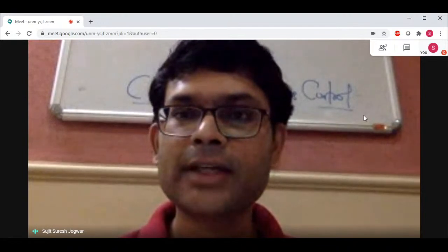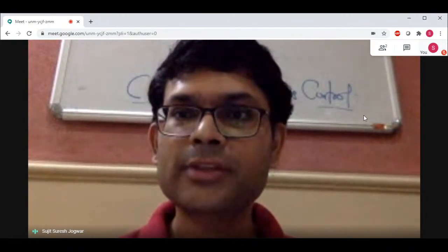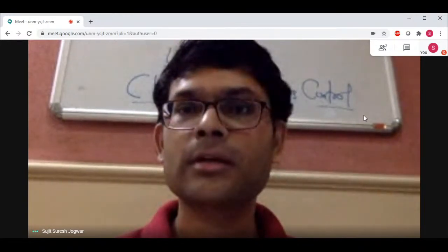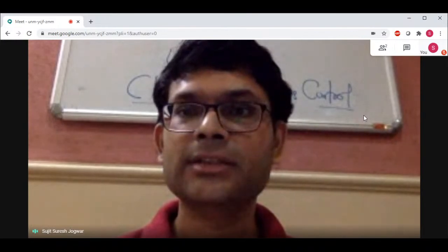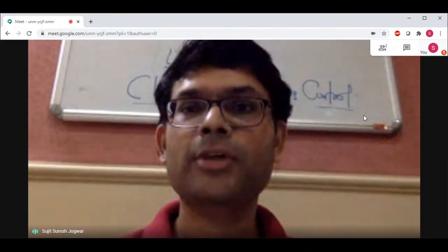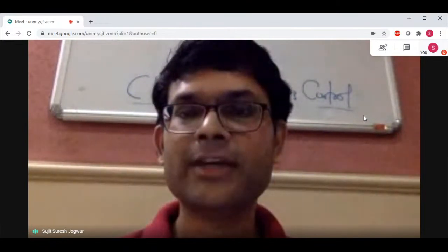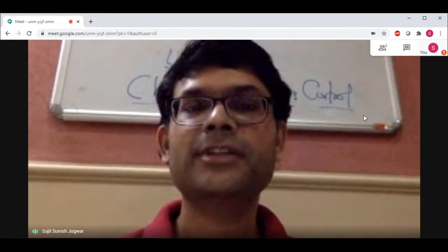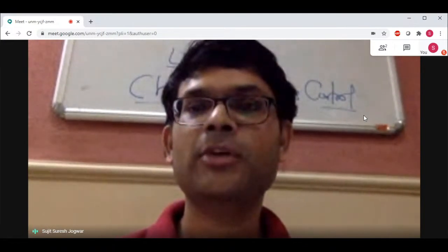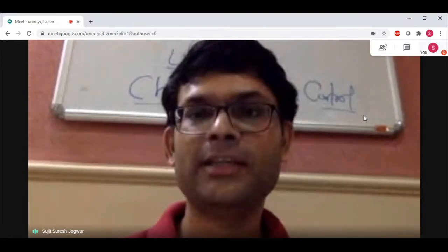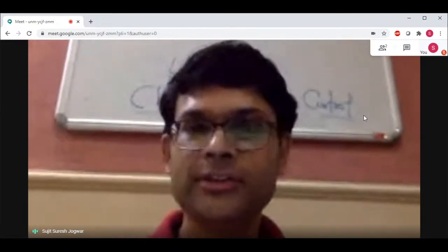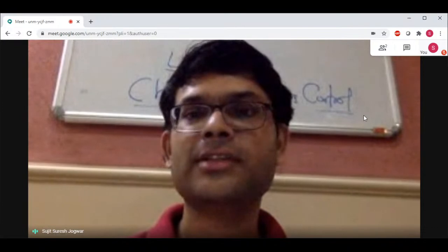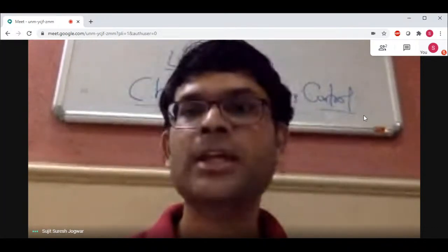Why does the slope of y(t) have a slope 0 at t equal to 0 for a second order system? The next question is by Sheena. She is asking about the slope of, I don't think it is ys, it has to be y of t. So y of t versus t, only if it's a first order process, meaning processes without any numerator dynamics, or the overall order of the system is 1, only then will the initial slope be non-zero.